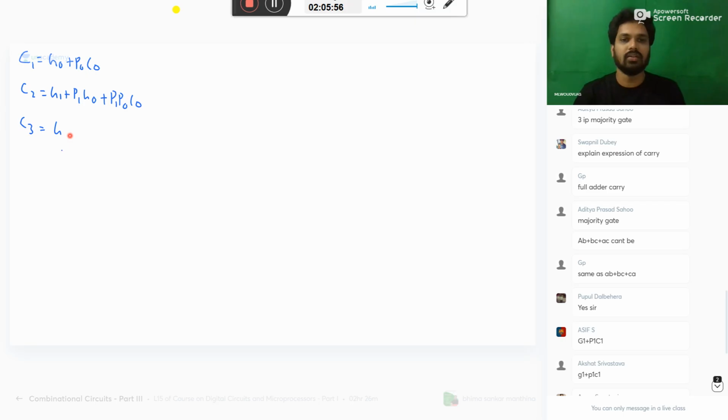So listen here. What is C3? It is G2 plus P2 G1 plus P2 P1 G0 plus P2 P1 P0 C0. Okay, so these expressions I copied as they are, nothing great. Now listen.